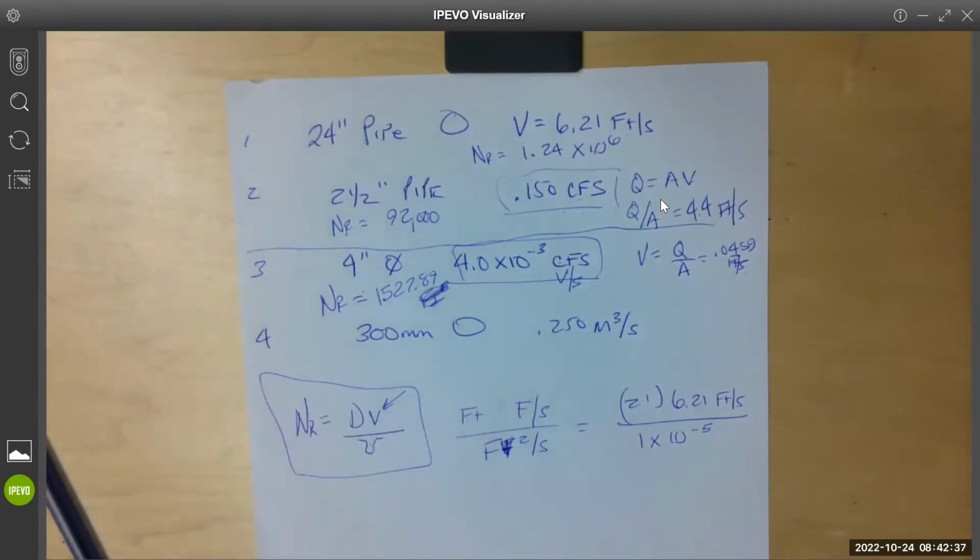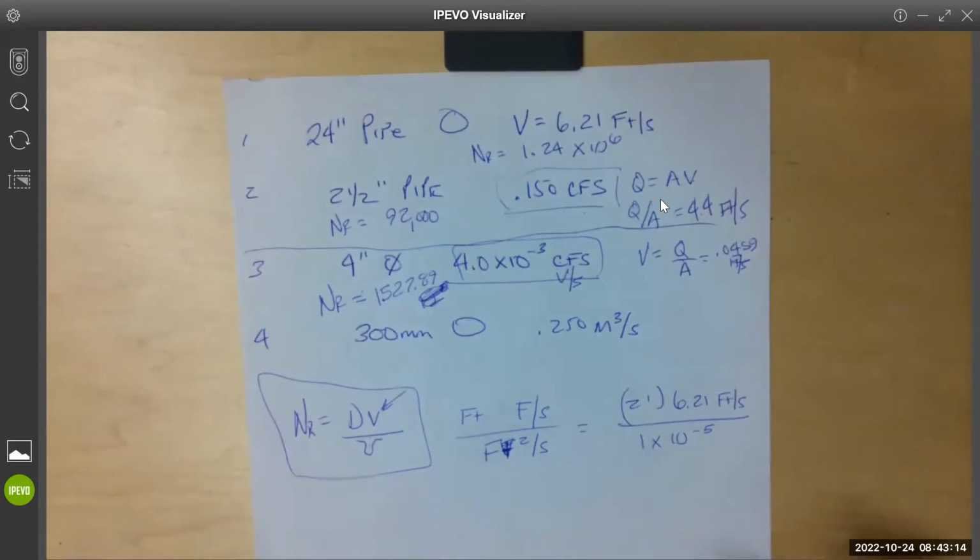You could, and you would just need to make that comment, like closer to turbulent, but it's kind of undefined. You just can't make that full decision. When it's between, it has a lot to do with the structure of the piping. So if it's between and there's hard 90s in there and it was kind of closer to 10,000, I would think that in the 90s it might be turbulent, then it goes laminar type of thing. So it's one of those undefined areas. If we're getting numbers in millions, then that's a relatively small window. Yeah, no, that's definitely turbulent.